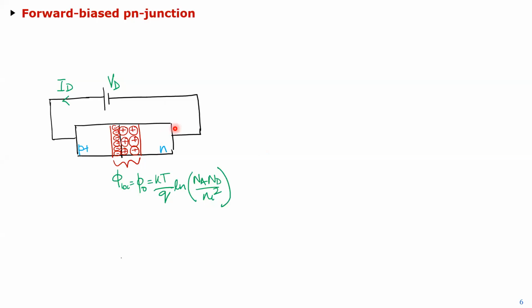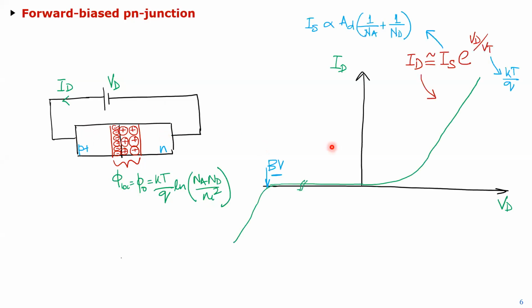Now, forward bias, I'm not going to go into the equation of it. In CMOS, we really never use the diode in forward bias. That's something we obviously always try to avoid. But if you take a PN junction and apply a positive potential with respect to the negative, and you keep increasing that voltage, that's essentially your IV characteristics.